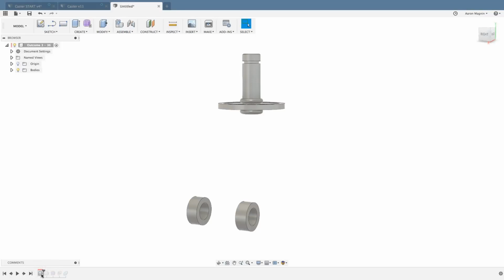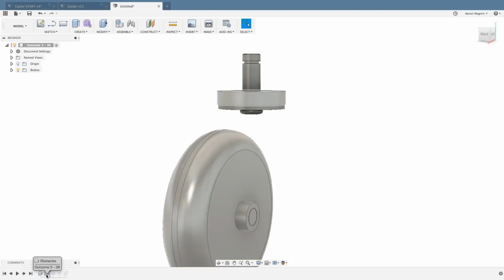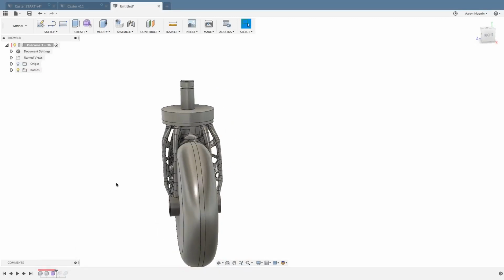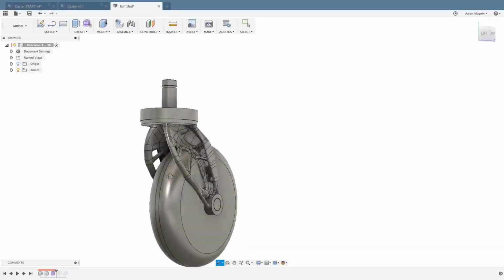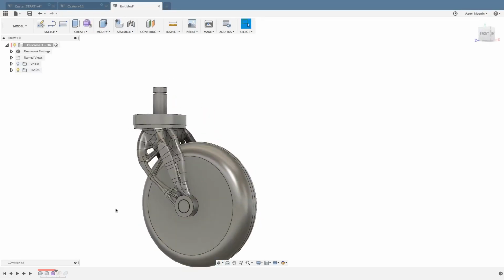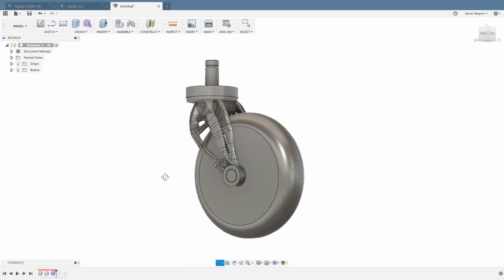You define those as preserves. So the very first feature you see in there is basically a series of bodies from the preserves. There's also the obstacles that are brought into this design history. From there, the T-spline body does all the craziness between the loading areas and the fixtures, and figures out the way to get there and have the correct strength ratios and everything.